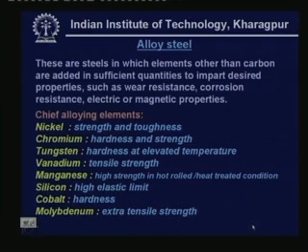So, you can see nickel, chromium, tungsten, vanadium, manganese, silicon, cobalt. Well, I just left out this one. This is molybdenum. Molybdenum also imparts extra tensile strength. So, a combination of different types of alloying elements gives rise to different kinds of alloy steel. Based on the use, environment, etc., you can use steels having the typical alloying elements I have just described.